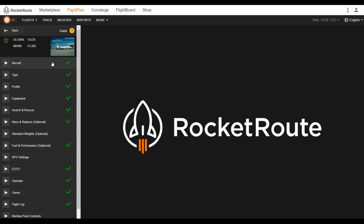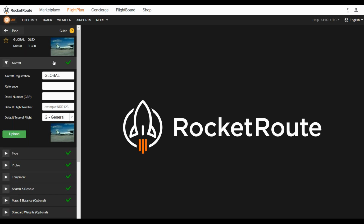So starting from the top, in the aircraft tab, you have fields like aircraft registration, reference, decal number, default flight number, and default type of flight. Aircraft registration can be adjusted if needed. Reference is quite a useful tool when you have several configurations of the same aircraft, so you can define which one is which.